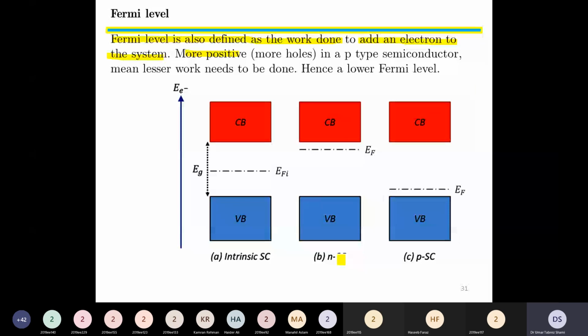So n-type material में we need large amount of energy, and in p-type material we need very small amount of energy to allow electron to fill in the valence shell. और n-type में we need large amount of energy so that this energy can be given to the electron, जो उसके बाद में कहाँ चला जाएगा? It will go in the conduction band.